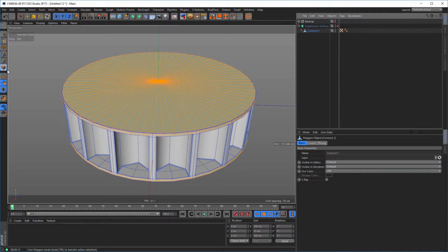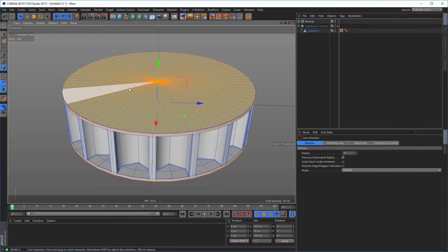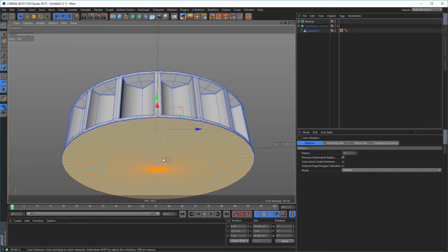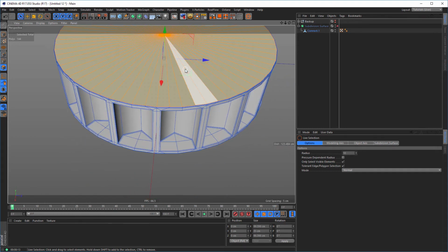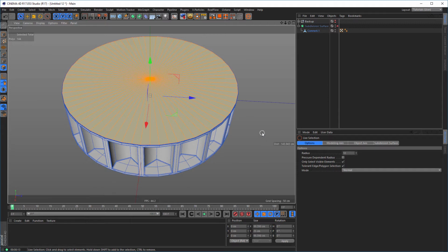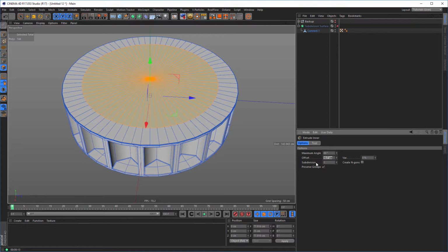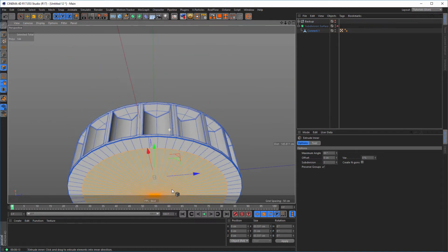Now polygon mode. Select this here and this here. Hold your shift key to add selection. Now I for inner extrude. Something like this here. Let's say 10 is too much. Offset of 8 should be okay. Yeah, let's say 8. That should work on the other side too.